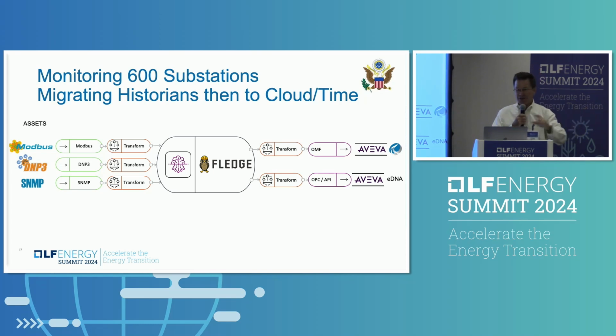Everyone who has a historian and is migrating to the cloud or migrating their infrastructure, whether you're migrating on your client side, IEC 61850 SCL, DNP3, Modbus, which will be the RTE use case I show you, or you're migrating on the integration side, the historian you're using, the maintenance system you're using, the cloud system you're using, you need data pipelines that support these migrations over time and manage your data. So this enabled them to keep eDNA alive for 2 years during the time of migrating those applications to the new historian, all in the same data pipelines. Make sense?